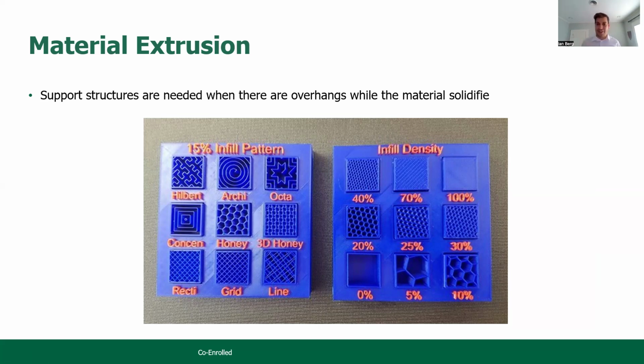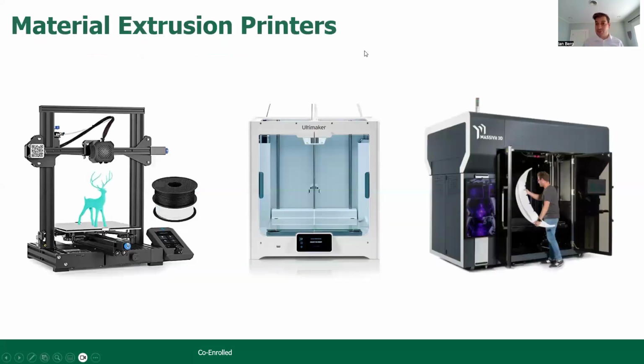And that's going to affect things like both the time it takes and the amount of material it takes to do the printing, but then ultimately it also affects the strength. So it's all about, is this just going to sit on the shelf and look cool, or is this actually supposed to have some kind of structural element that you need to achieve? And so that's, again, your choice as a designer, usually in that slicer phase, where you give it the mesh and then you tell that slicer software for its instructions what you want it to do with the inside.